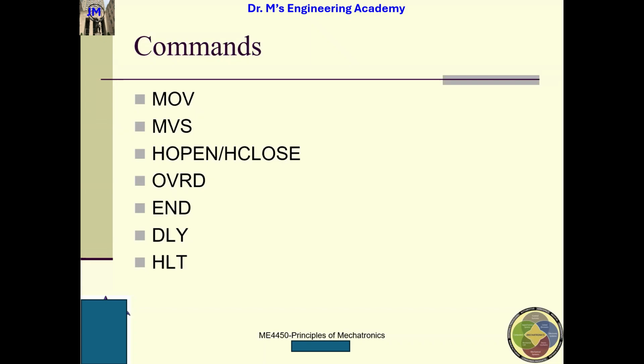Can you write down, guys? If you do not use halt, when you start running, the program will be running again and again. However, if you put a halt in front of this END, then this program will be running only once, and then it gets stopped. I want you guys to write down.